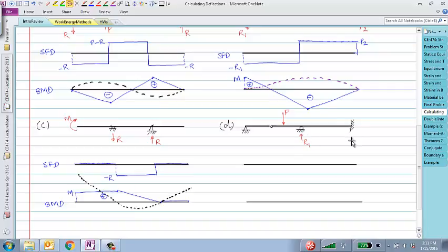Down. Why down? Because it's resisting it. Right. So if this support was not there, this load would want to make this go up, which means that this support is trying to push this down. Any guesses on which one would be greater, R1 or R2 in magnitude? R1 looks like, yes, I would agree. It looks like it would be greater. But again, that depends upon the lengths of those segments and the actual loads applied, which you would need to solve exactly to judge more accurately. But here, once again, we'll make these assumptions and go forward.